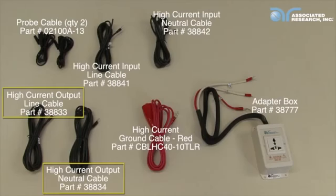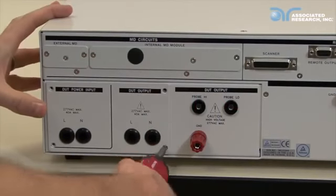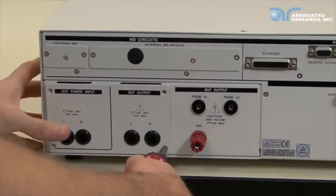You will only need to use the high current output cables for the line leakage test if your DUT draws more than 20 amps of current. Otherwise, you can use the line leakage adapter box to simplify your connection to the DUT. We will be using the adapter box to make connections to our DUT. First, we need to connect an external power source for our line leakage tests.